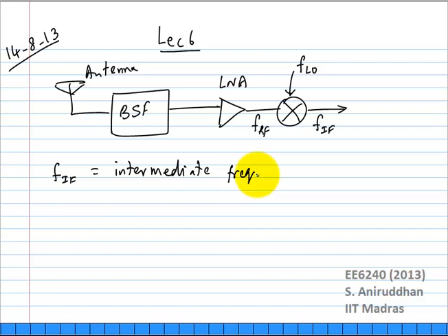After this, what would you choose to do? So you have brought your signal down, you have amplified it a little bit. Okay, you have brought it down in frequency, then what else? Maybe some more amplification is in order. Why not do all of it up front before the mixer? Huh? Stability issues. What kind of stability issues can you imagine here?